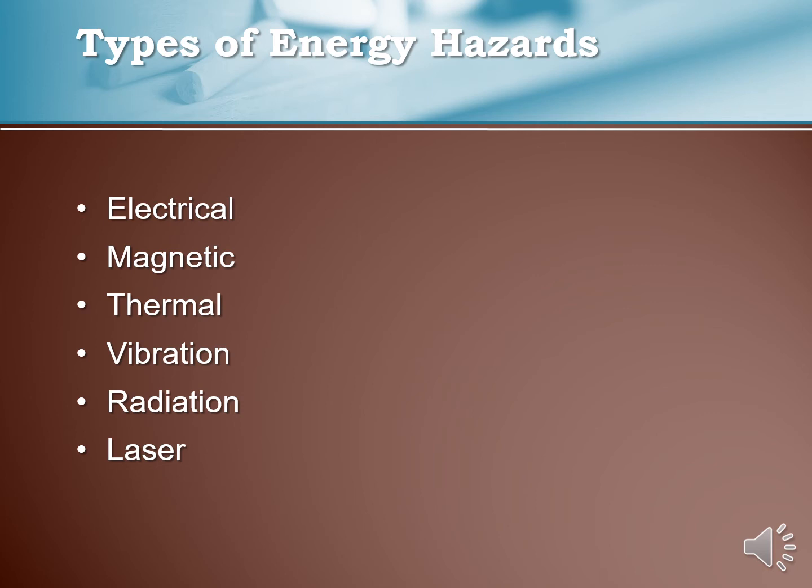In addition, there may be thermal hazards, such as burns or scalds from contact with extreme temperatures, like in welding or science classes, flames, or even radiation. Lasers also present potential eye or skin injuries and potential for burns or puncture wounds, as well as laser air contaminants. We're starting now to see laser cutters in tech. These processes should be enclosed and properly interlocked so the operation cannot start until the human is behind closed doors, protected, and the exhaust system is running.